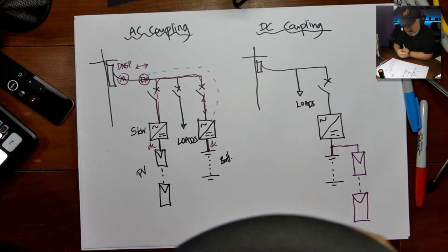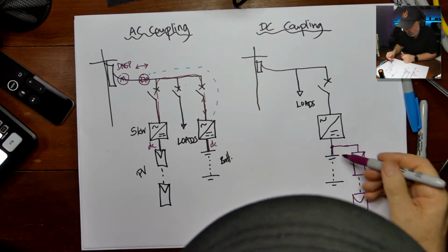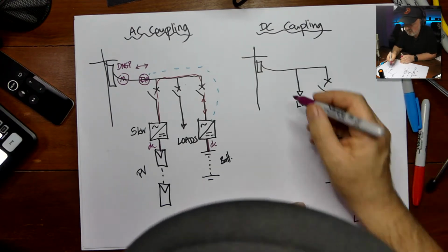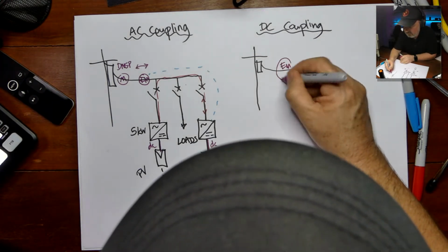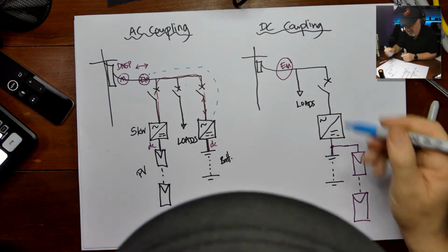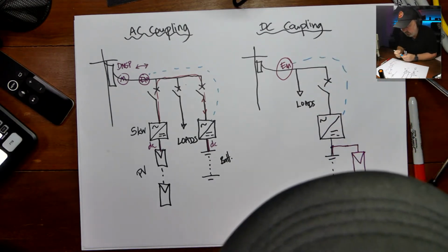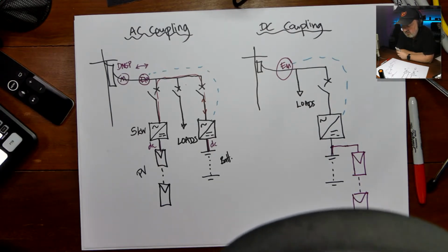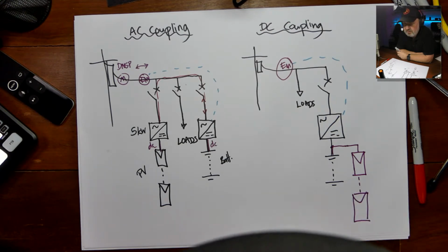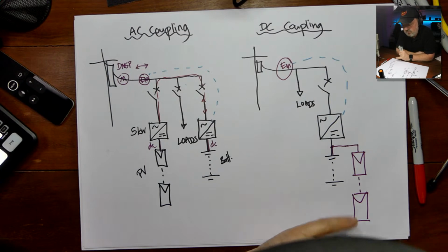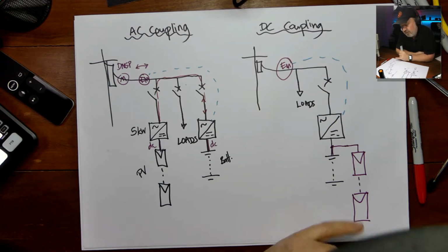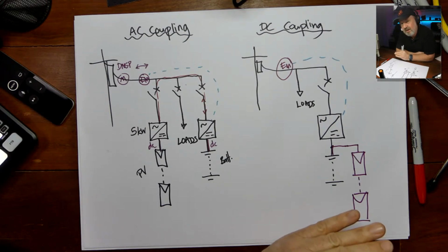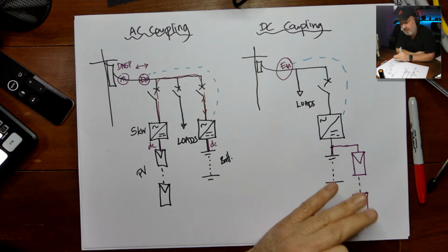Equally, this system needs that energy meter as well. The reason is that this battery system here doesn't know that you're using any power, so it doesn't know to support the loads. And so we need our energy meter supplied with the battery inverter system here that communicates with your battery inverter and tells it when to charge and discharge to support the loads, or you can even do some clever things such as what they call time of use charging, which is where you're allowing the battery to be charged from the grid as opposed from solar. Not all products have this capability, but if you've got a big price differential between off-peak and peak, you may actually choose to use some grid power to charge your batteries.